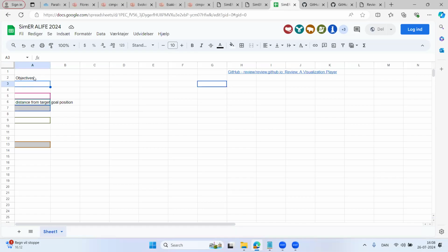Yeah, exactly. Distance from target to goal position. I'm really glad somebody put it exactly that way, to goal position, because think about what your goal position sensor might be. You could put a little RFID tag on the ground, and as the robot gets over the RFID tag, it knows the signal strength and it stops at the exact correct spot. I'm going to say the only sensor you have though is a distance sensor to the wall. So that's slightly different. So distance from target to goal position, that's definitely the objective.